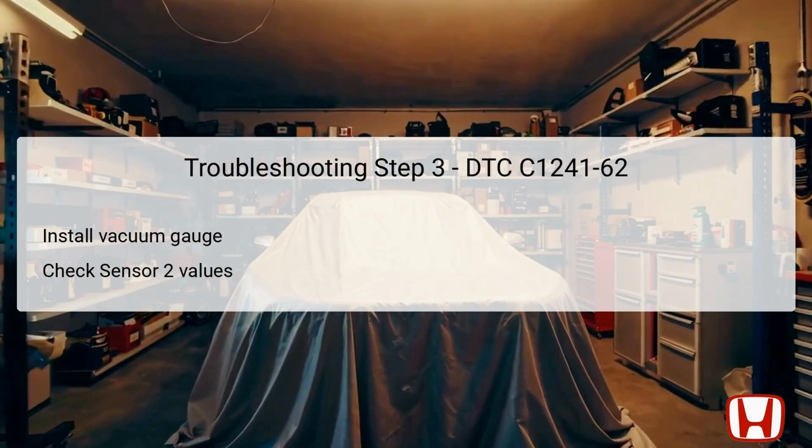Just as with sensor 1, the values should match with the readings on the vacuum gauge under normal conditions. If there is a significant difference here, it is indicative of an issue with brake booster pressure sensor 2. This insight helps narrow down the focus for repairs or replacements needed.